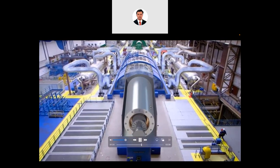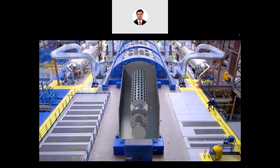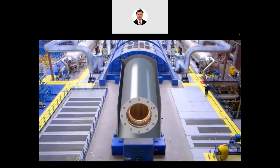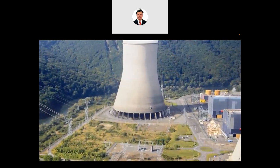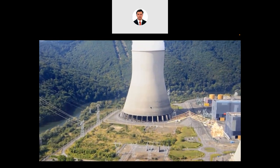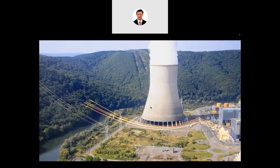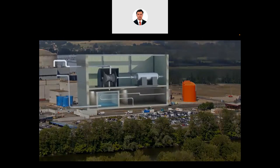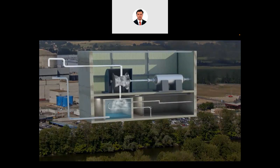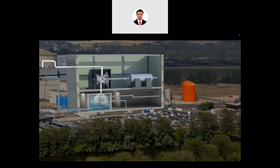This steam turns a turbine, which turns a generator. In the generator, the interaction between the electromagnets of the moving rotor and the copper coils of the stationary stator produces an electric current. A transformer then boosts the current's voltage to between 225,000 and 400,000 volts, thereby facilitating transmission over the grid's high voltage power lines. When leaving the turbine, the steam is turned back into water by the cooling system. It is then returned to the steam generator to begin a new cycle.